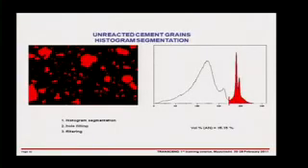What's very important is that we have to do then, say, 100 images. Sorry, it's not on that slide. We should now do 100 images, because in the image next to it, we may have, say, 15%, the image next, 17%, and so on. So it's only by averaging about 200 images we can get a good estimate of how much unreacted cement we've got, and we can use that to calculate the degree of hydration.